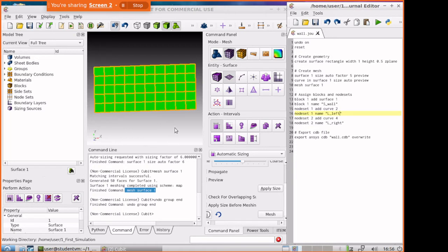I want to say L left has a prescribed temperature of 25 degrees centigrade, and I can only do this if the boundary has a correct or a unique identifier. And this is what we're defining here for the curves. So for the lines, left and right, and for the bulk material, so for the interior region. Let's start with the interior region.